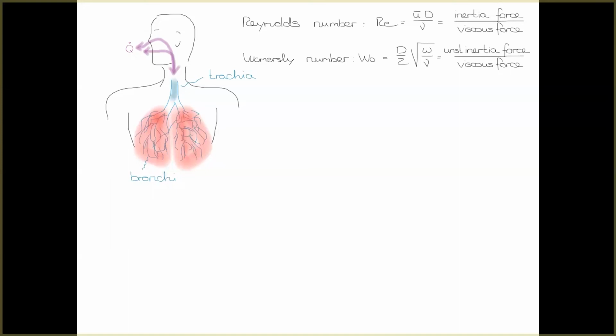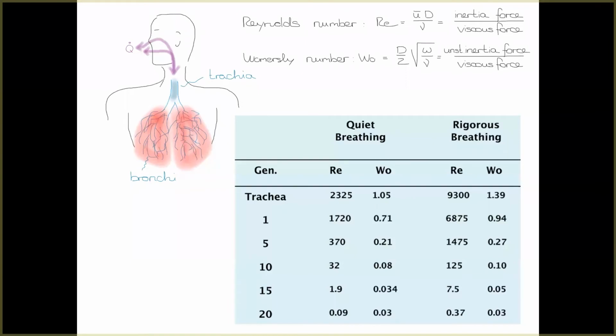But for a given boundary condition, we can assume quasi-steady conditions. For example, if you do a simulation and the Womersley number is very small, you can, for one state of the geometry, just do the simulation as a steady state simulation, and that's good enough. So that's a second number. We come back to that because we need both in order to make our argumentation.